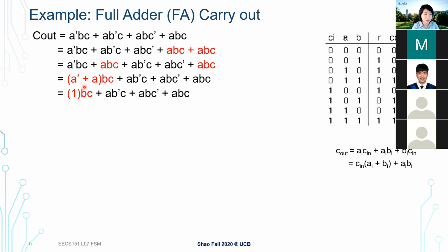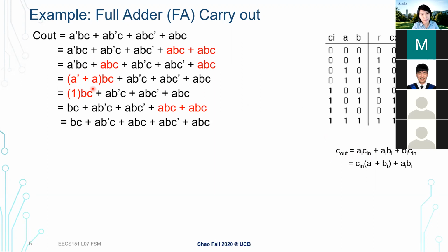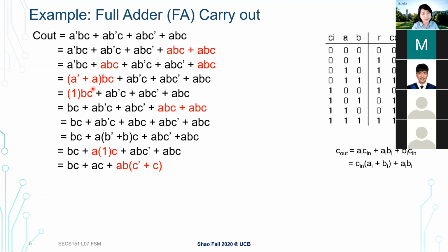So we can actually eliminate one of the inputs in this expression. Keep doing that, go through this. After the class, it will be an interesting exercise, and then you will see how we get to the final expression, which is the same as the majority gate expression that we're using. So this is how we can use this uniting theorem to do logic simplification, to simplify our design by looking at the Boolean equation.